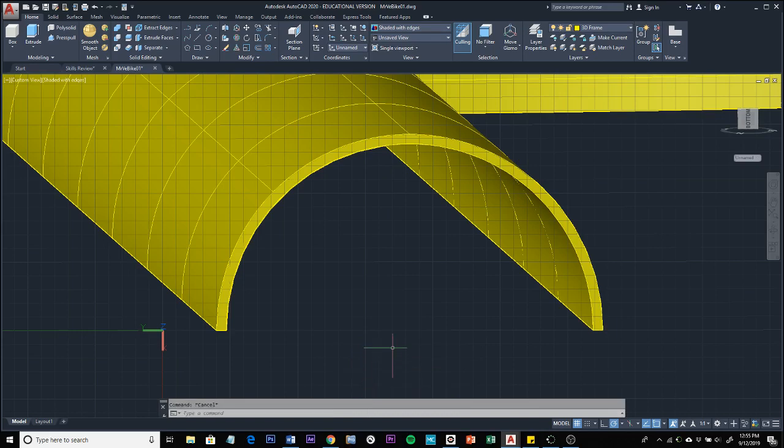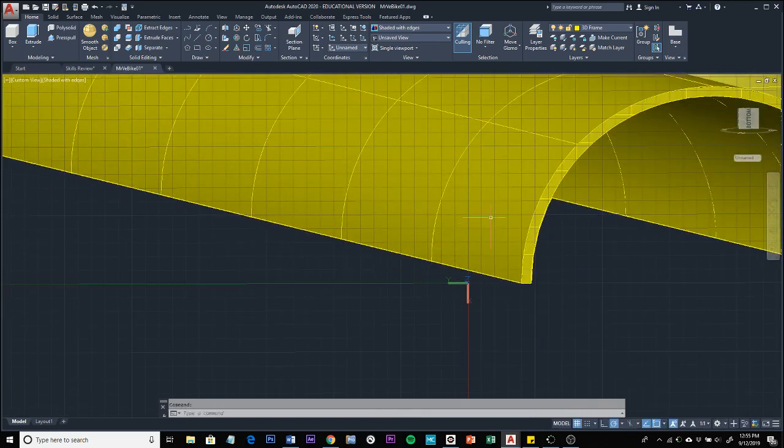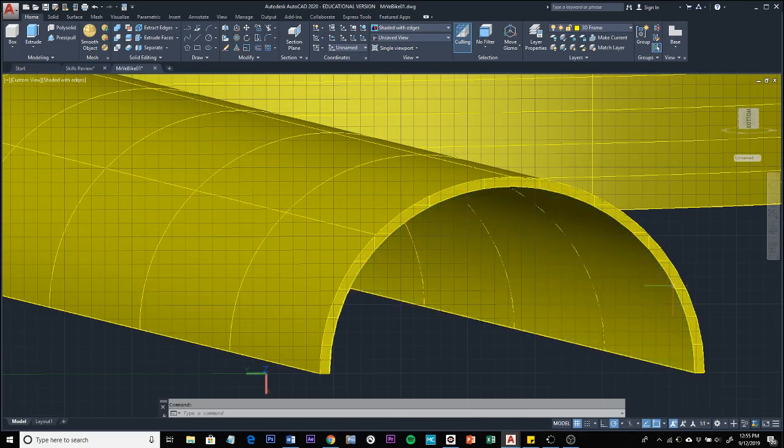So I'm just going to type it in, CONV, find convert to surface, click on that. Pick your region, and then press enter. Now it has kind of the hash pattern similar to the other surfaces. It's kind of a grid line to it. And if you hover over it, it should say surface, but it doesn't. It says region.